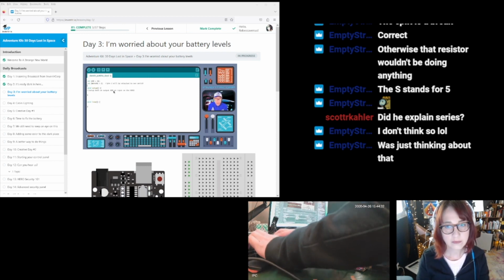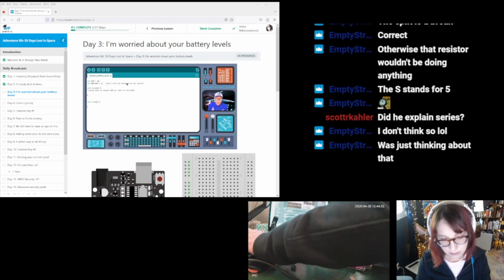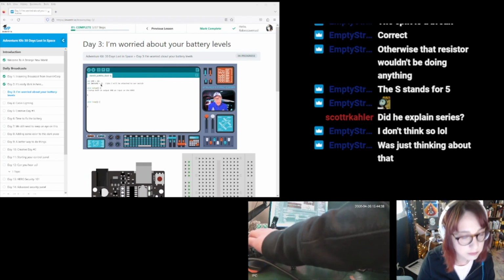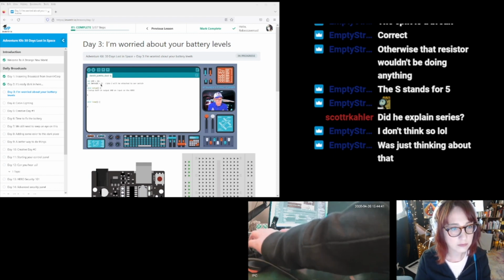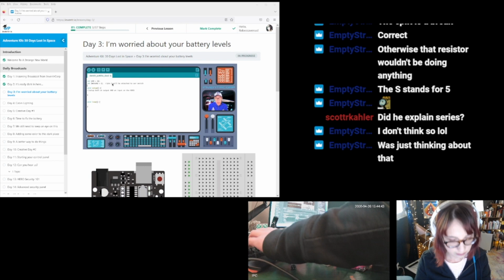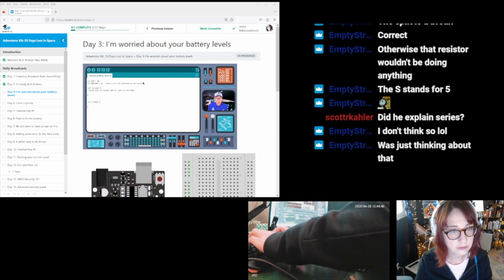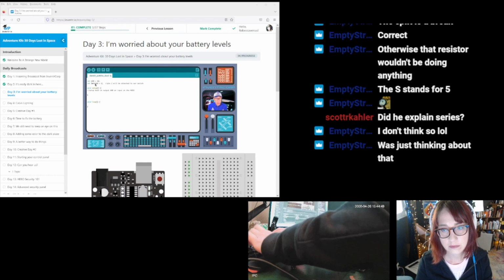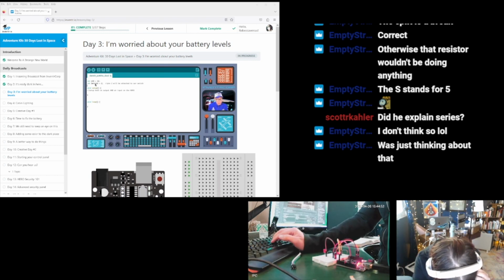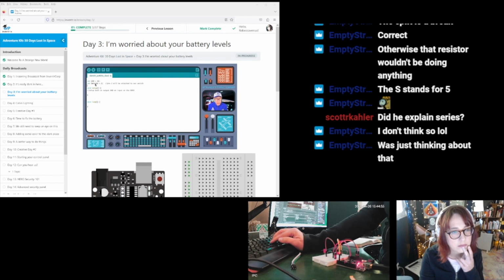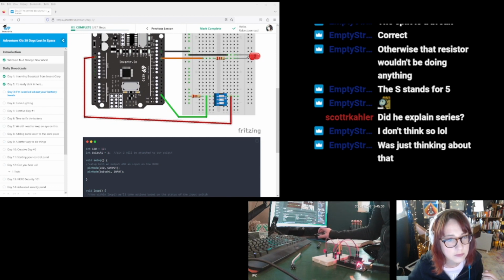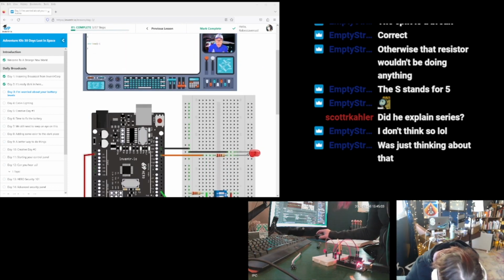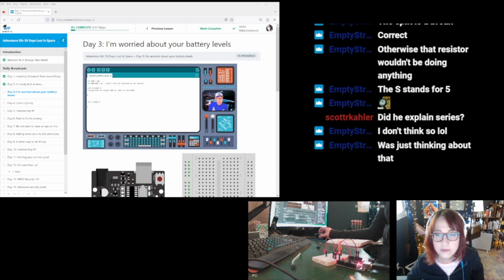You'll notice that we have a comment next to this just to remind us that we're setting switch 1 equal to 2, which means that pin 2 will now be the pin on the Hero that we're going to connect to our switch. Now, we have to ask ourselves, well, what are we going to do with that pin 2 that's different from what we did, say, with pin 12? And in order to understand that, we want to see what we're going to do in the subsequent setup and loop functions on our Hero.